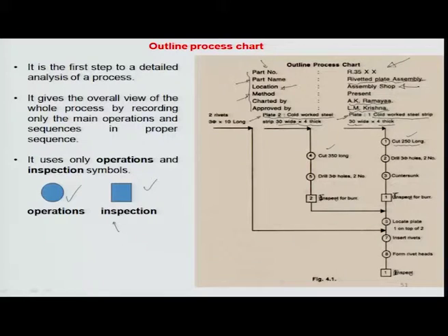So, cutting of plate 1 is at 250 millimeters long, a sample cut out of the whole steel strip. Now, the second plate is cut at 350 millimeters, okay, and then you have drilling. So, there is another operation, drilling, where a certain hole size is drilled, and two of these holes are drilled on both the sheets. So, sheet 1 is drilled at two different locations and sheet 2 is drilled at two different locations as well. And then the first one, which is on the top, has another operation of countersinking, so that the rivet head can go inside and there is planarity on the surface. So, we have machined a countersink on the top sheet, and then we inspect both the samples, plate 1 and plate 2, for burrs, okay.